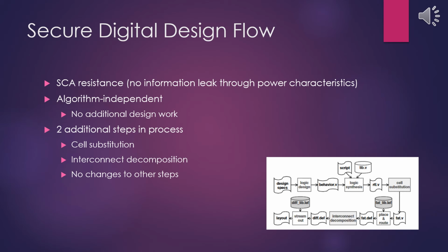One solution to increasing a circuit's side-channel resistance involves using a secure digital design flow. This process uses WDDL logic and multiple differential pair routing to reduce or eliminate the information leaked through device power characteristics. The design flow can be seen in the figure on the bottom right, and it's algorithm independent. It only requires two extra steps: cell substitution and interconnect decomposition. Other than that, it does not modify the design process at all. The actual circuit design and functionality is not changed and requires no additional modifications.